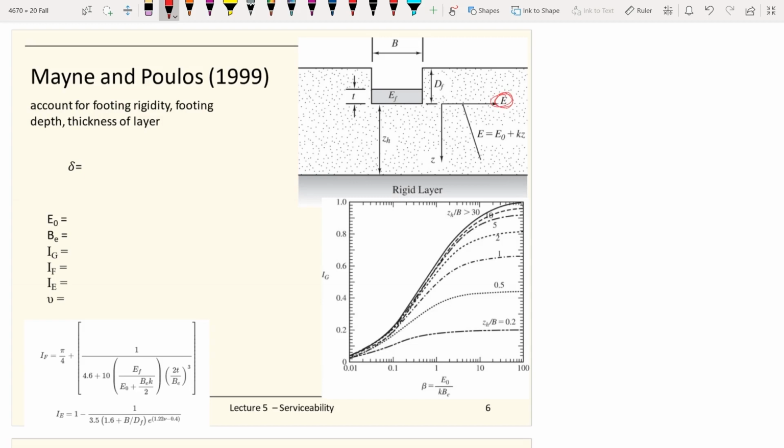So you see, they try to model the modulus even within the same soil here. They try to model the modulus with a value that's increasing with the depth, which is true because the deeper you go underneath our ground, the stiffer and the stronger the soil is. So they make some adjustments over there.